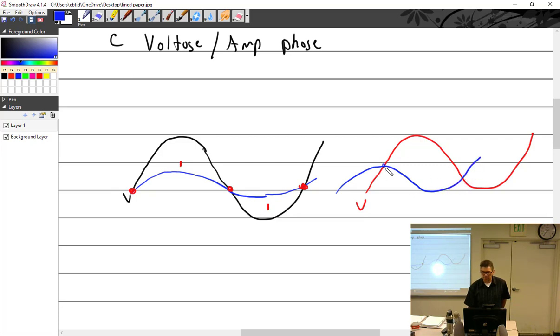Where the peak is here and this is over here, and it's like, what did I just draw? Nothing really lines up. This peak is just off from the 0 point. That's way out of phase. They're happening at different times. If I drew it really nicely, I could have drawn the peak right over this. If the peak is right here and the 0 is right here, then it would be 90 degrees out of phase, where the volts are peaking out and the amps are building up.